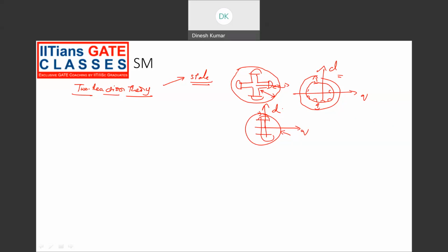So the armature reaction increases. In salient rotor machines, the air gap length is minimum along the D axis and maximum along the Q axis. Therefore, the armature reaction is maximum along the D axis and minimum along the Q axis. Earlier we have seen the armature reaction reactance. The armature reaction drop is represented by a reactance, that is the armature reaction reactance. Earlier we represented it by a single reactance value.